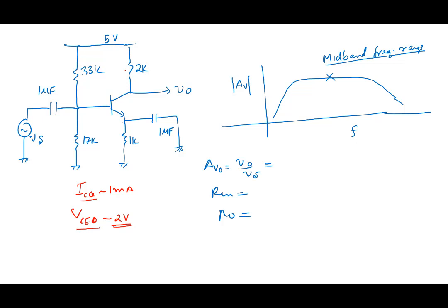Yeah, you can write AV0, Vin, V0, Rin, R0. These are straightforward. Minus gmRC. Find out how much it is. R pi, how much it is. RC, how much it is. Write down these values. These are typical values for your amplifier.